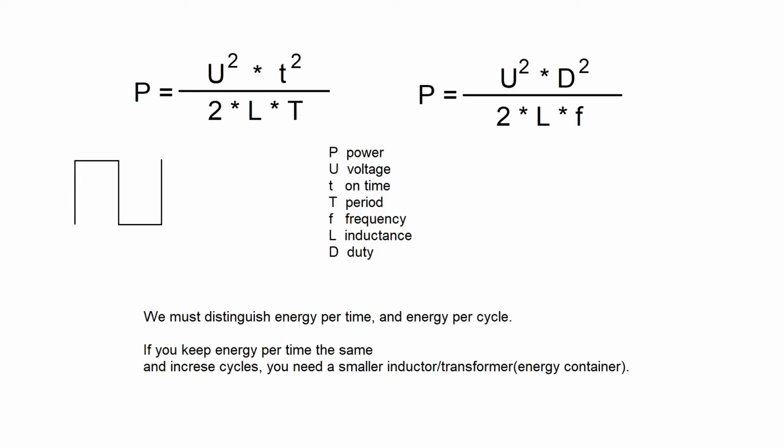Since you're making a power supply, it's pretty important to know how to calculate the power. So these are the equations for power. Since this L is in the denominator, you can gap the core to increase the power of your power supply.